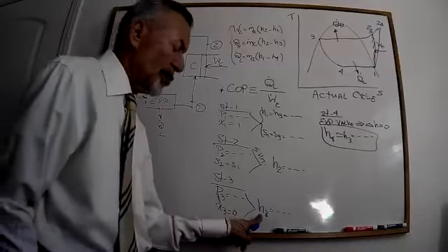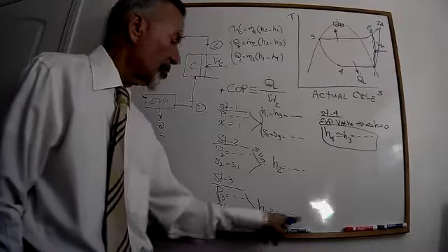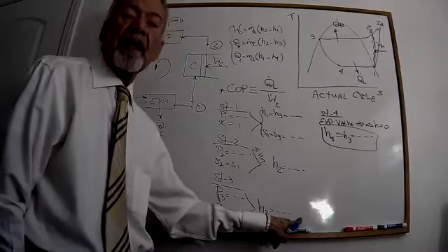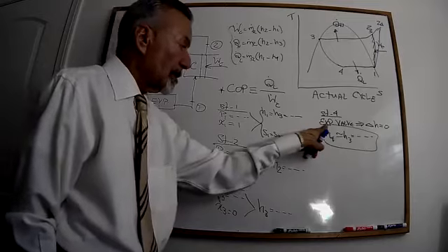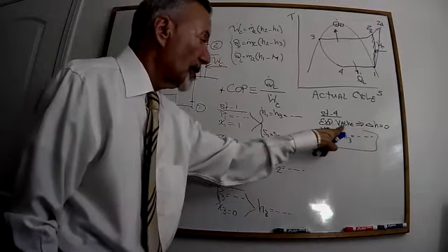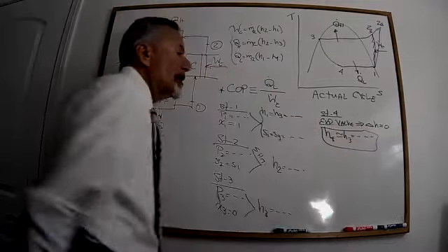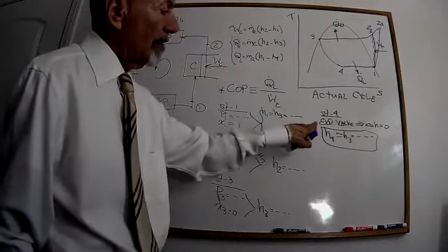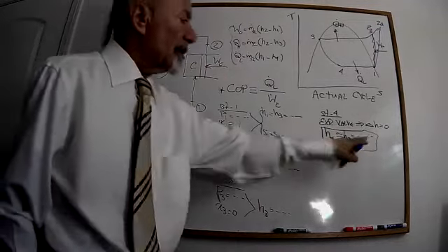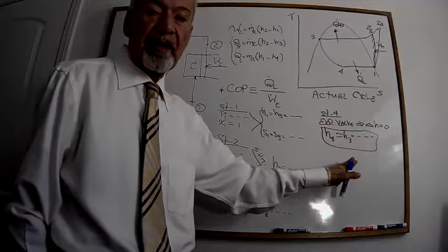You cannot, when you get to H3, say this is equal to H4. Because third-party readers are going to say, why is H3 equal to H4? This is what you're telling them why. So again, it all comes down to the communication, how well you communicate with a third party. By writing this statement saying because of the expansion valve, delta H across the expansion valve is equal to 0, therefore H4 and H3 are the same.